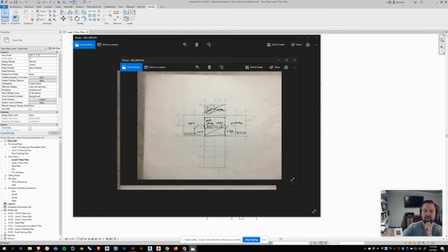And why do we need two fire stairs like this? Well, here's a good way to think about it. If I only had one of these and there's a fire right here and I'm over here, I can't get out, right? So if there's a fire somewhere in between, people are trapped over here on the second floor. They can't get out. So you're going to need to add a stair over there.